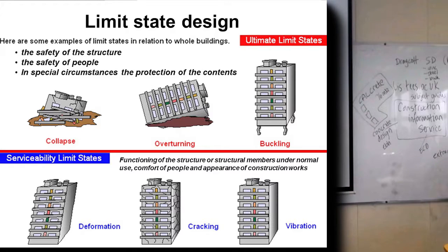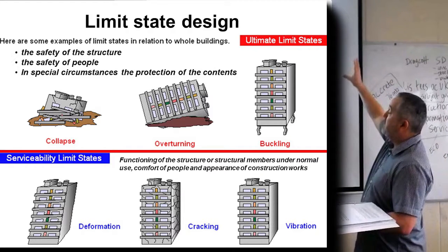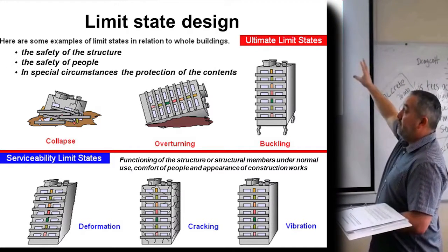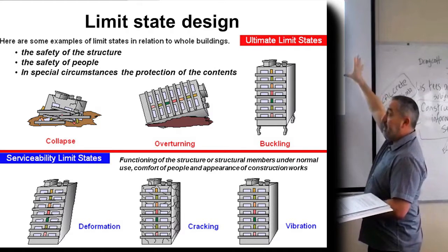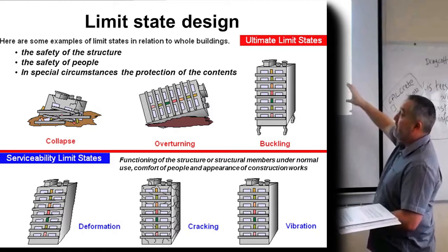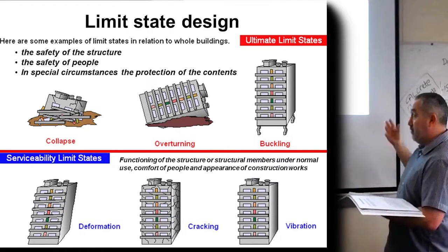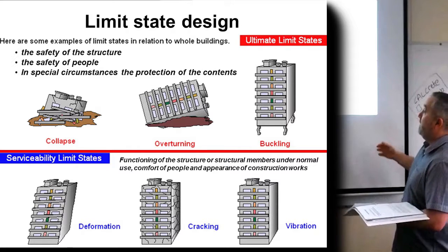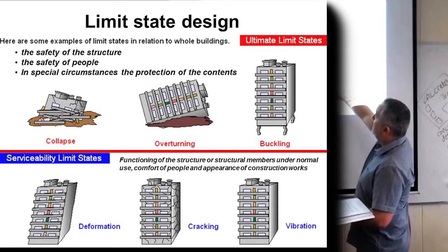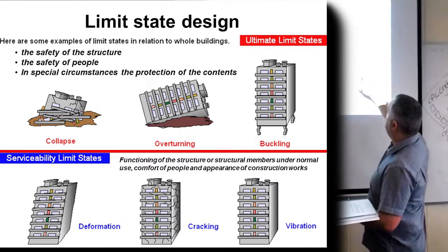But we talked about limit state. He talked about limit state design. So you've got your ultimate limit state design. This is where you're looking at the safety of the people, where the whole thing's collapsing, and you'll find that there are factors of safety that you apply for that. And then after that, you've got your serviceability limit states, which we care about in the UK. Some countries don't consider them, but this is where you're looking at the comfort of people and the appearance of construction works.